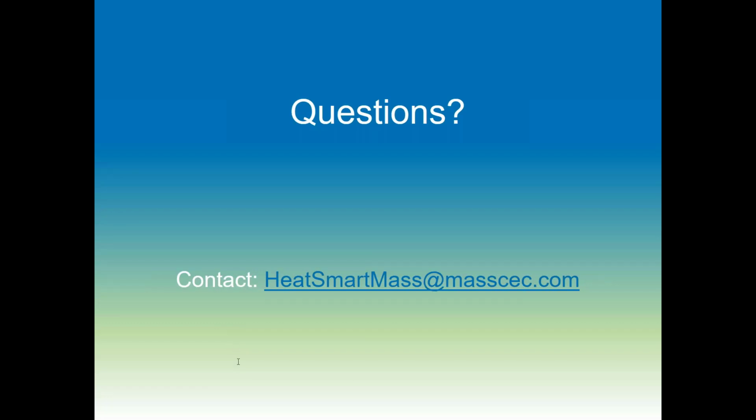Have air source heat pump water heaters been considered for this program, and why were they not included? So heat pump water heaters are a somewhat different technology, where typically they're located in a basement or other indoor area, and they rely on waste heat from a boiler or furnace to provide the heat source. So because of that, we're really looking at systems that can ultimately be fossil-free, rely on fossil-free electricity, and because of that, they have not been considered in this program.